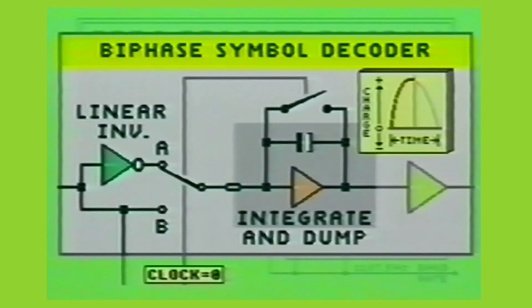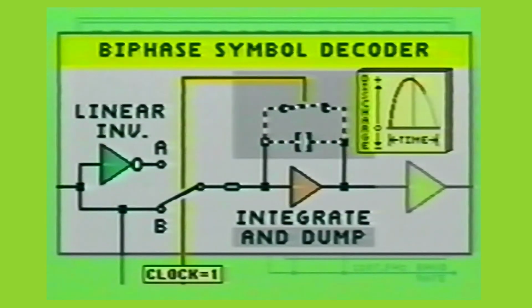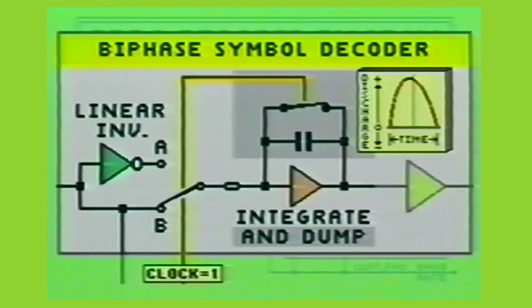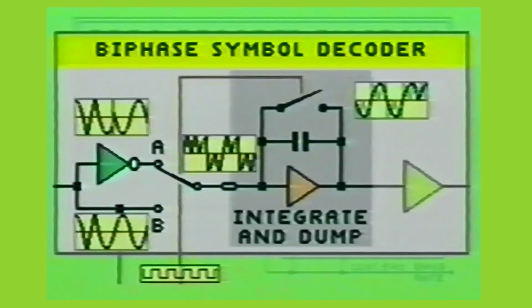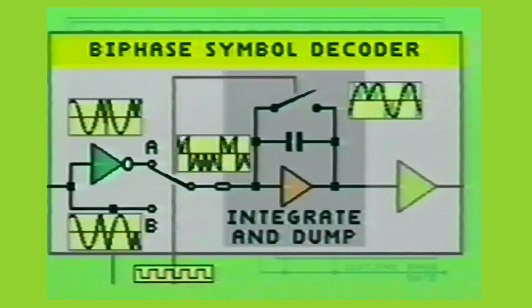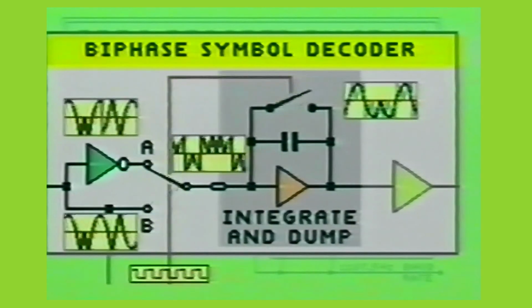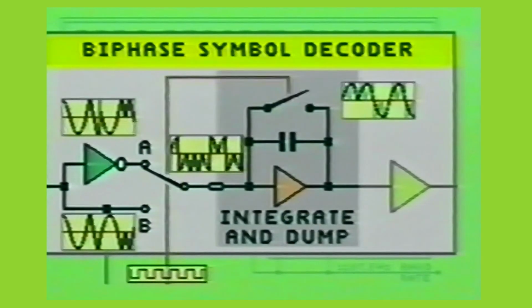The dump occurs when a high logic condition on the clock line toggles the switch above the capacitor to a closed position, which discharges or dumps the capacitor's charge. This dumping resets the integrator prior to every summing operation. The integrate and dump process is the decoding equivalent to the logic conditions found at the output of the RBDS encoder's NRZ to polar impulse converter.